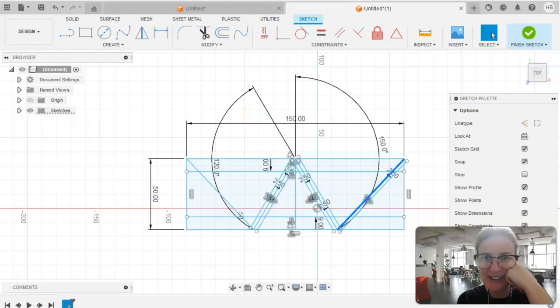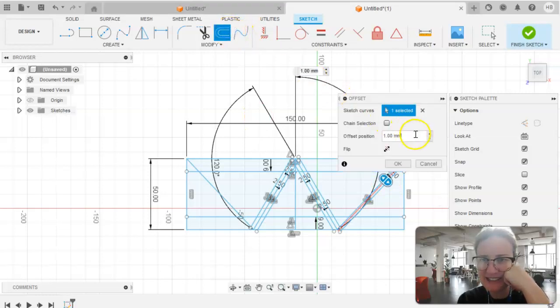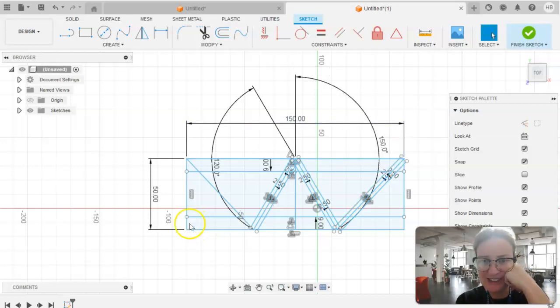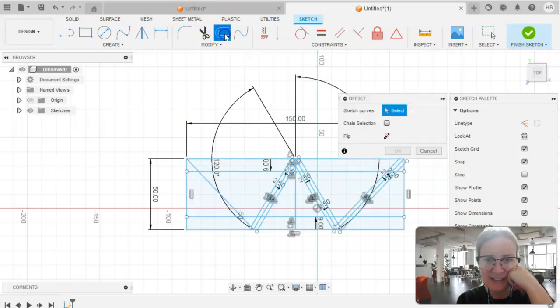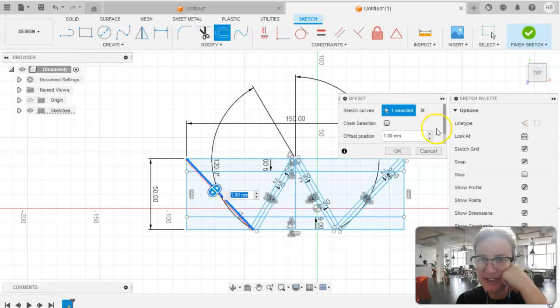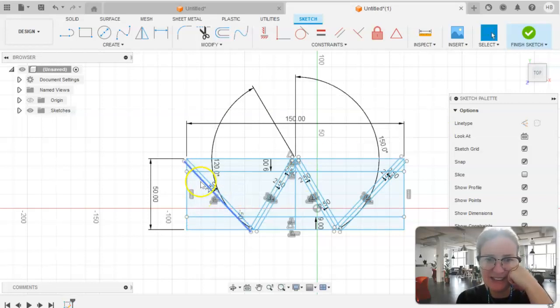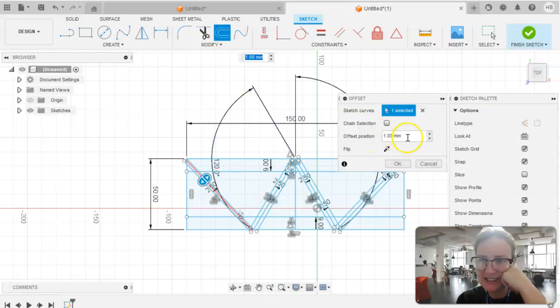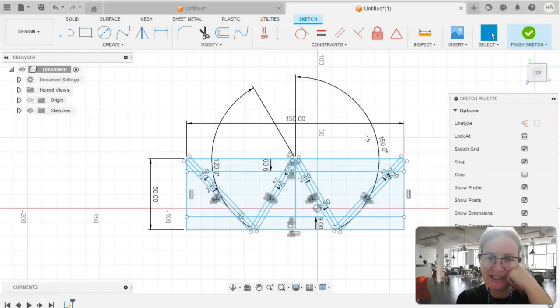And click on the line again, offset, negative 2.5, and almost done, offset this last one, 2.5, enter, and that same line, offset, negative 2.5, enter. Okay. So what we've now done is we've created weight to our initial line drawing, a thickness.